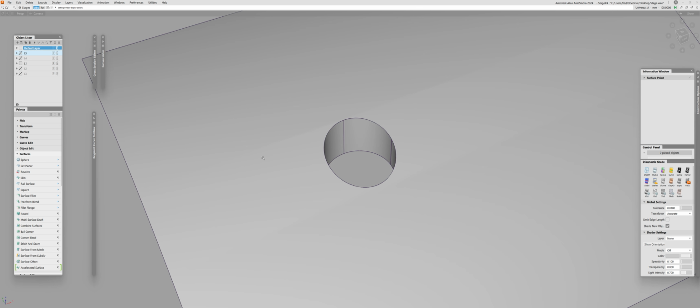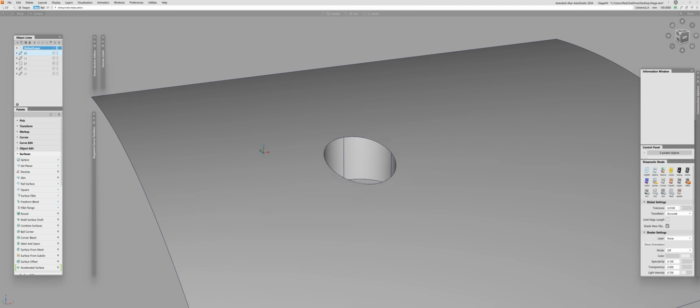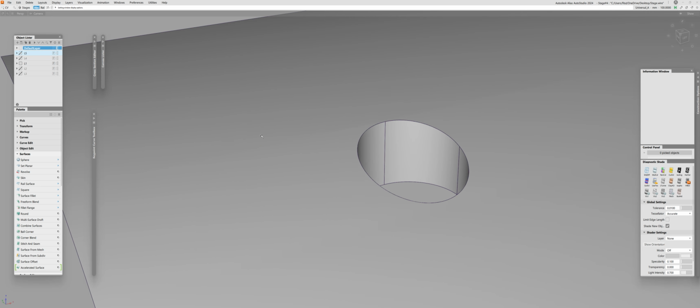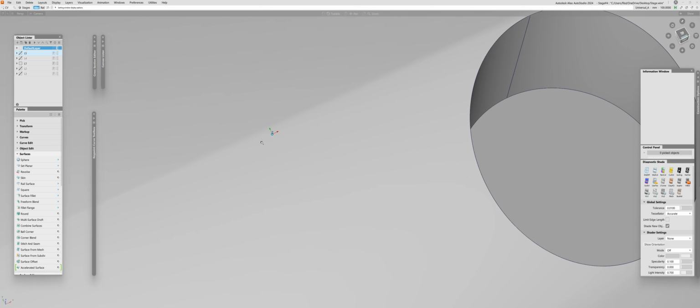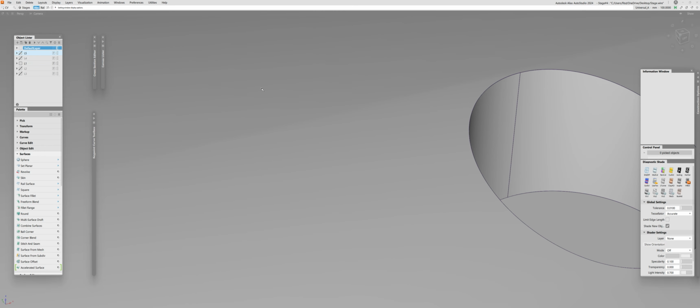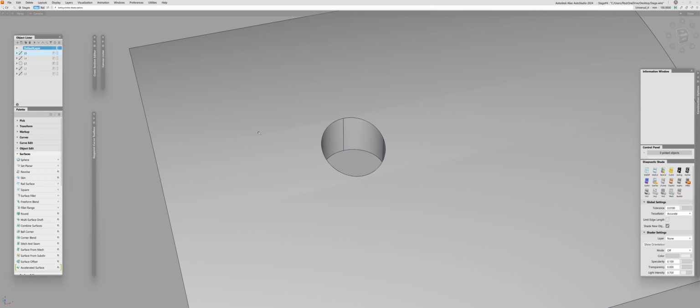So the reason why we have the issue in this specific situation is because of the algorithm we are using. It's not Catmull-Clark, by the way. It is a different one and depends on the kernel and the tool you use. The algorithms are different. I believe they don't have any commercial names. They are built within the company itself, but they all share the same similarity: these built-in real-time tessellators in the CAD systems operate based on the curvature of your surface. So the smaller the curvature, the less geometry it will bring. The more curvature it has, the more geometry it will bring. And as I said, it's basically universal. Now the details can vary. I don't know what the actual code of the algorithm is, but it's kept secret. It's very specific to the company.